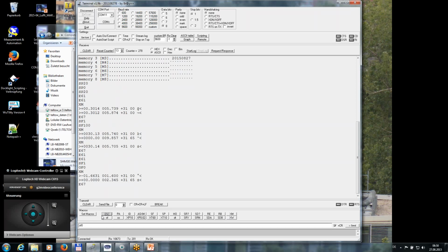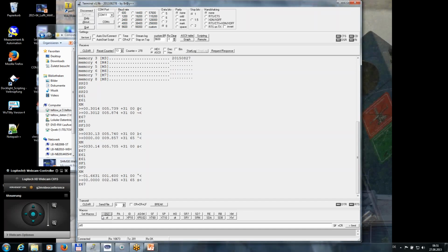So the first measurement was a kind of starting measurement, and now I have measured the distance from the sensor to the ground, which in our case is 1 meter 66, corrected with this 20 degree inclination angle. And of course, this is a minus distance. Why? Because now I do a zero measurement. So I determine the distance to the ground with the offset measurement.